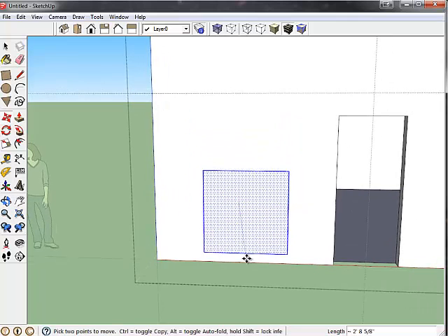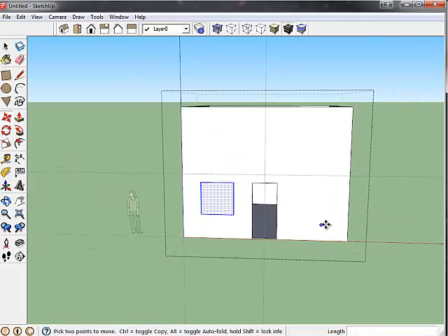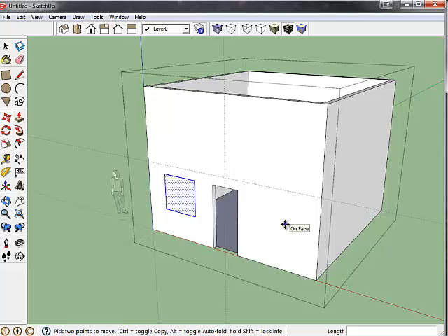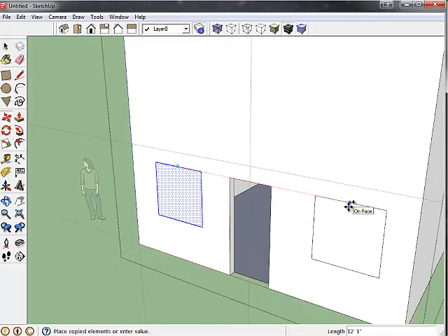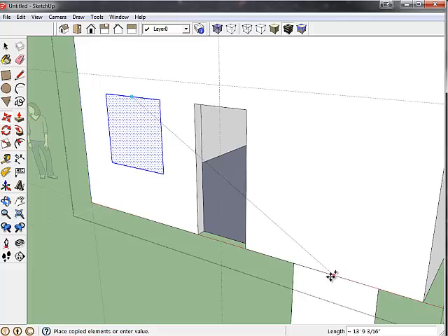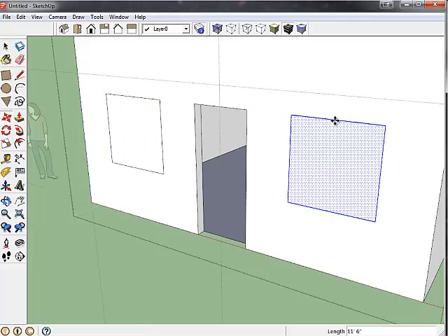Once we're set there, we want to make sure we're set on the bottom. Drag up, and you'll feel it snap into position. Now in this case, we don't need to create another rectangle over here. Instead, we can just copy the one we already have. So I'll press Control, I'll drag it straight over. I'll move down to the midpoint where I wish to snap, and straight up until I get to the point where the two lines intersect and I'm centered.